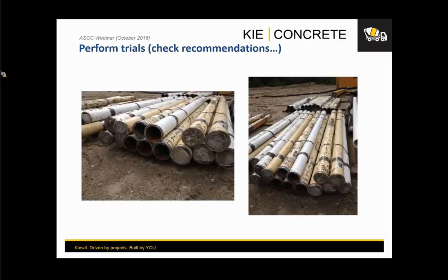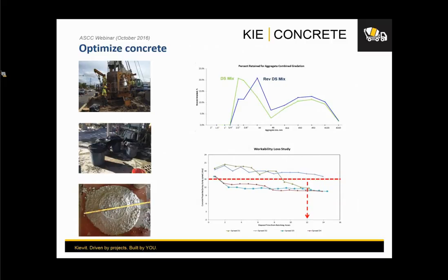So what happened here is obviously we didn't have the right mix, we didn't have the right lubrication in the mix, and the type of operation we had for that mix was not right because this is a stop and go operation. You're not continuously flowing concrete. You're placing and stopping, placing and stopping, placing and stopping, and you have 700 feet of slick line with a lot of viscosity modifier because somebody recommended that would be a great pumping aid, right? Be careful with that.